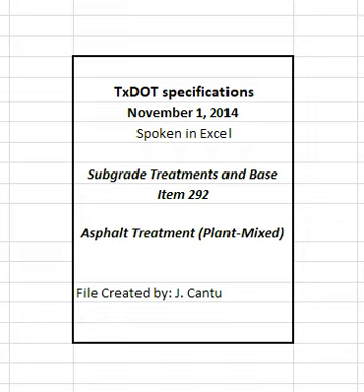4.6.2 Production Testing. The engineer will perform production tests. 4.6.2.1 Operational Tolerances. The engineer will determine compliance with operational tolerances. The gradation of the aggregate must be within the master grading limits for the specified grade, except that a tolerance of 2% is allowed on the sieve size for each mixture grade that shows 100% passing in Table 2. Ensure that the asphalt content does not vary by more than 0.5% from the design target.